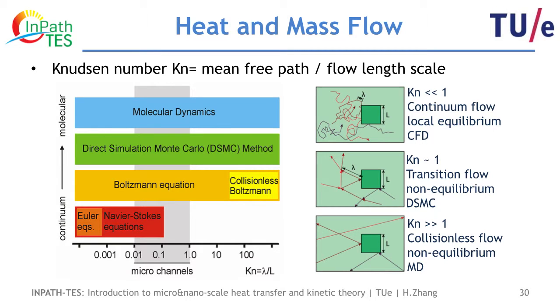In a physical system, transport phenomena is an important feature to be studied. In kinetic theory, which will be introduced further in this lesson, the Knudsen number helps to determine whether statistical mechanics or the continuum mechanics formulation of fluid dynamics should be used to model a situation. The Knudsen number is defined as the particle mean free path divided by the flow length scale.